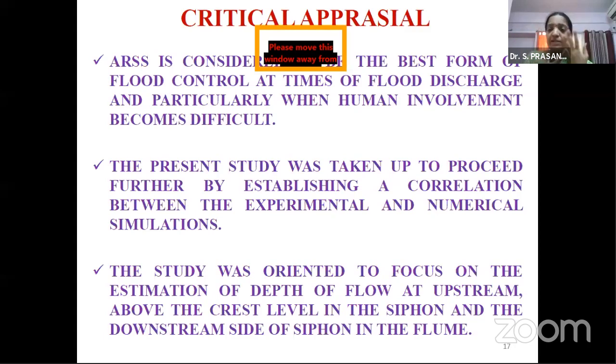As I told you, when you have your results or contours domain open, you can see very clearly what parameters you can get. You can get dynamic pressure also, absolutely, there is no doubt in that. But one important point is that dynamic pressure can only be visualized in the form of contours, as I have shown you the contour of volume fraction and the velocity magnitude.